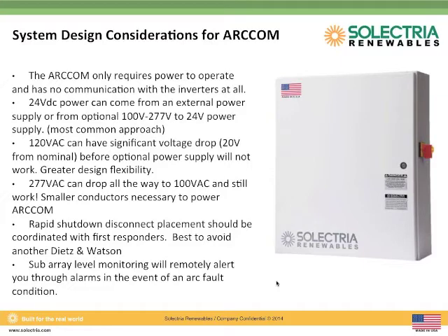Perhaps the contactor has gone, perhaps the 24-volt power feed is now compromised from a million different things. So perhaps a conduit splice has fallen down and sheared that conductor. Maybe we've blown a circuit breaker, what have you. The 24-volt power that is required for the Arcom combiner box and various other products such as Arcom is typically really hard to run for long distances in DC form.